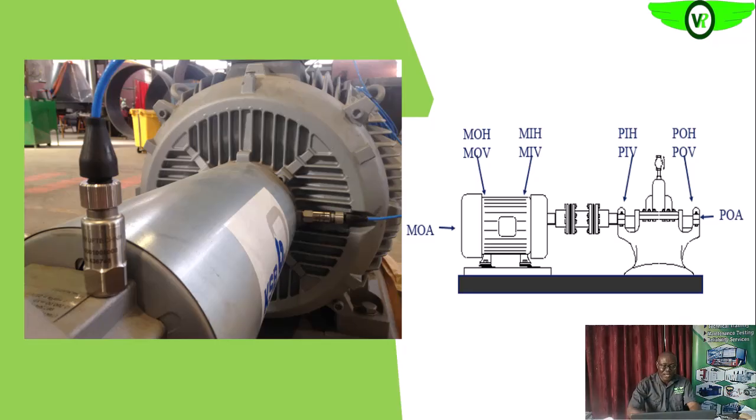So here are the physical example of the accelerometer, okay, or vibration sensor. And you see that they are placed on the bearing housing, okay. So the orientation or the direction of measurement, it is usually such that we'll get the most information from that housing. So as you can see on this diagram, we have the driver, which is an electric motor, and then the driven equipment, your load, which is the pump.